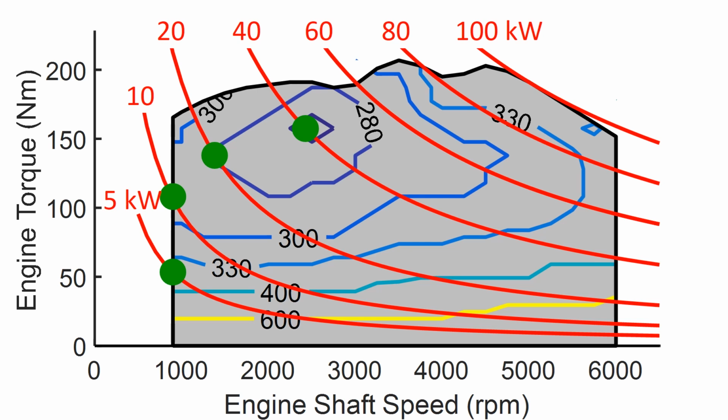As the power increases above 40 kilowatt, the best possible fuel consumption will increase a little. At 60 kilowatt, it is 288 grams. At 80 kilowatt, 320 grams. At the peak power of the engine, there is only one operating point to select from, and there the fuel consumption is about 350 grams per kilowatt hour. If there is no engine power, 0 kilowatt, the lowest speed is the most efficient operating point.